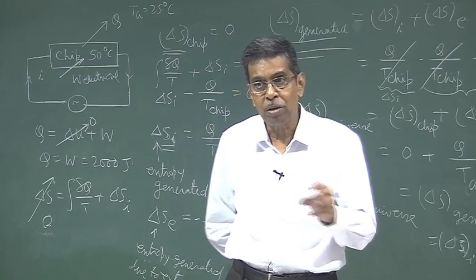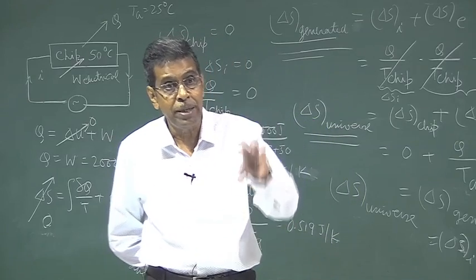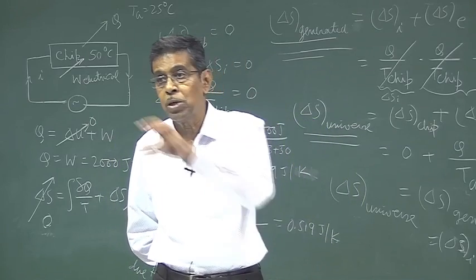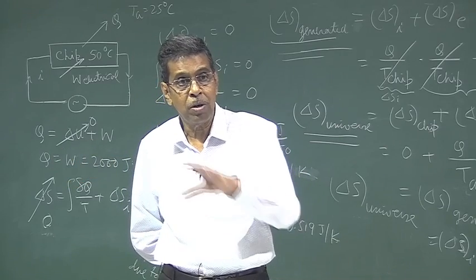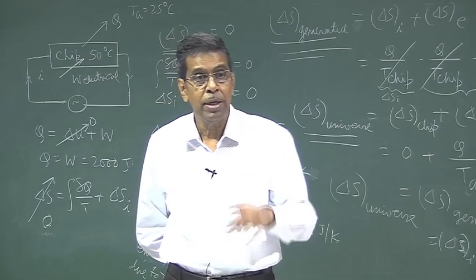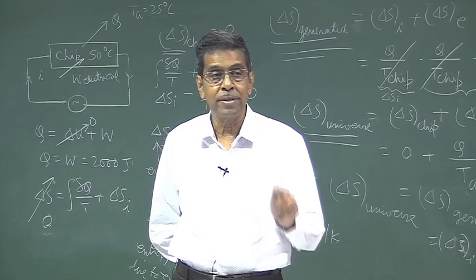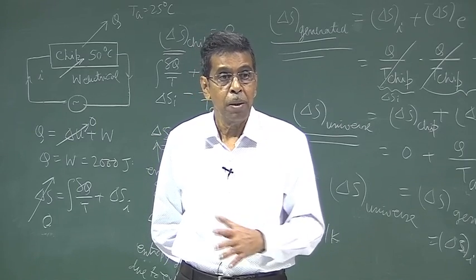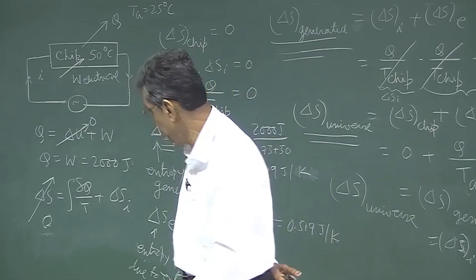But heat cannot be converted into work by the same amount. That means the equal amount of heat cannot be converted into the same amount of work in a continuous process by a cycle. A thermodynamic cycle is required for continuous conversion. But in any single process, heat can be converted into work. That concept should be there.